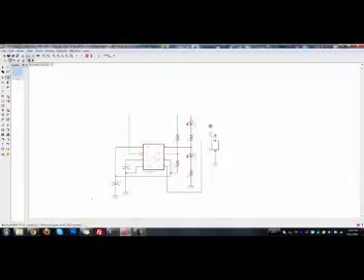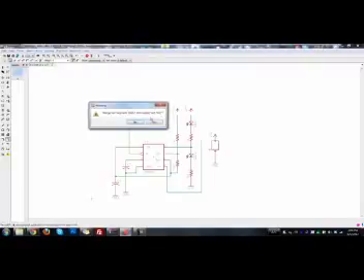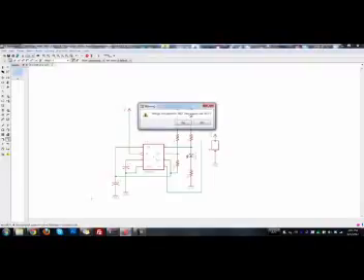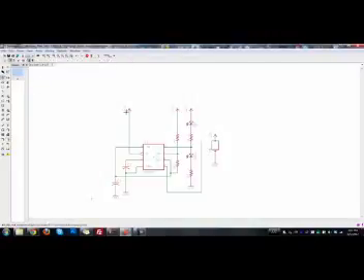Just duplicate the supply. Set it up everywhere where you want it. And attach a wire. And then, for here, let's say we don't want these lines crossing because it doesn't look that good. What we can do is rotate VCC and put it right in there, just like that. And that just keeps everything looking a little bit nicer.